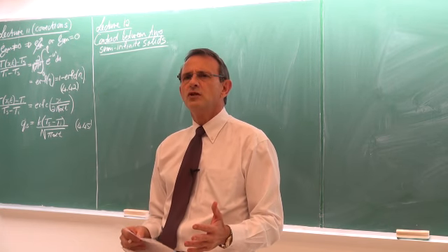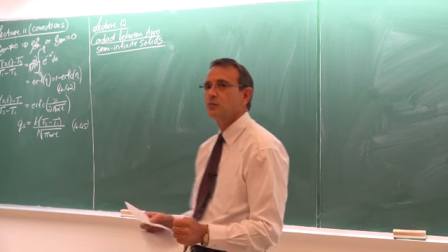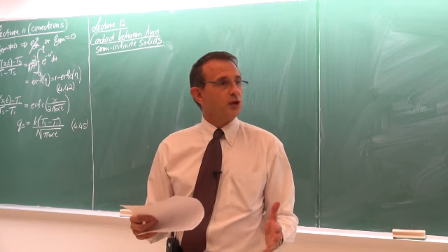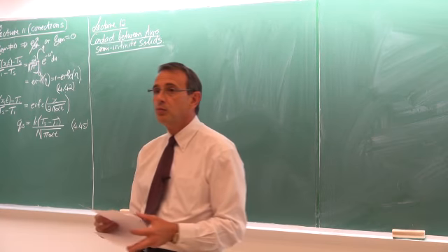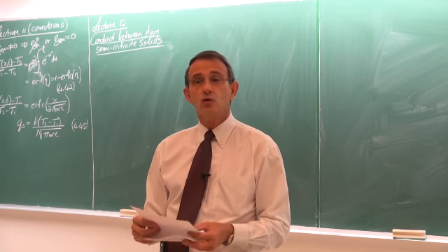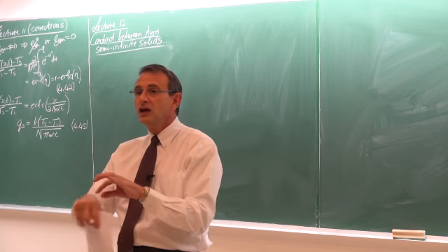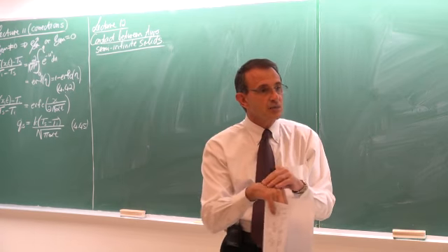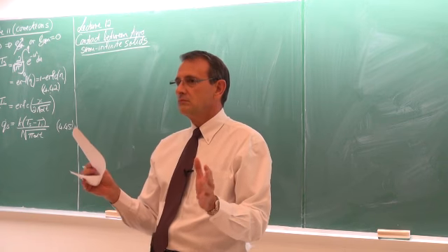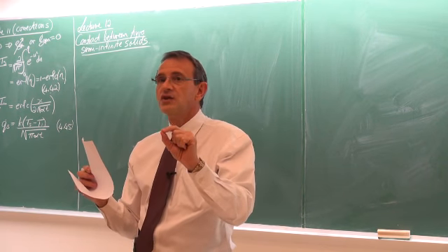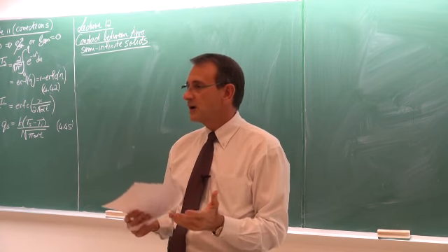But except for those, you might think, well, there are not a lot of applications for semi-infinite bodies. Well, there are. Large plane walls, for example, can also be approximated as a semi-infinite body, and many other bodies. For example, your own body can also be approximated as a semi-infinite body if you're interested in the temperature changes very close to the surface. So any body where you just want to see how the temperature changes very close to the surface can be approximated as a semi-infinite body.